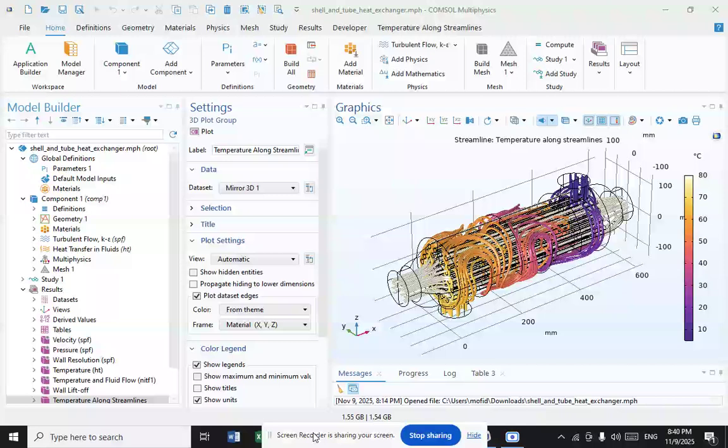The shell side. Plate and shell technology offers high heat transfer, high pressure, high operating temperature, compact size, low fouling, and close approach temperature. In particular, it does completely without gaskets, which provides security against leakage at high pressures and temperatures.